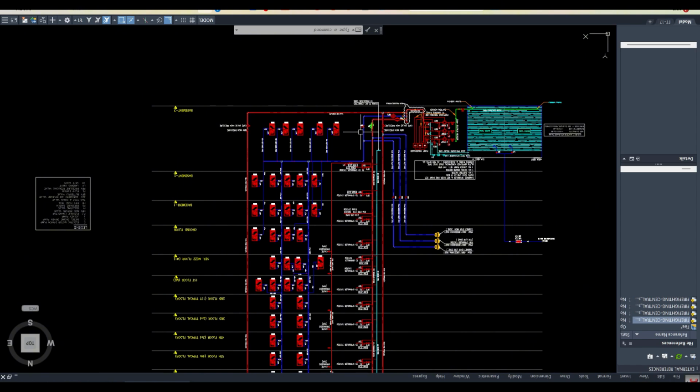In that, the first class we call landing valve system. I will explain it now, but first understand this, you can write it down also. Then the second is the hose reel system. And the third is the combination of landing valve plus hose reel system. So that is class 3. So there are three classes of firefighting system, and this excludes the sprinkler system because that is a completely separate system.